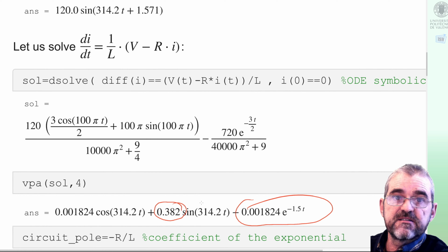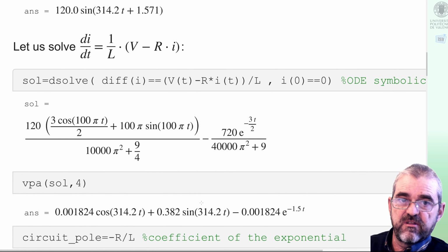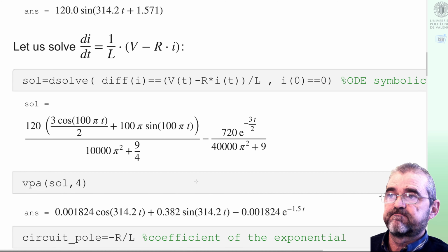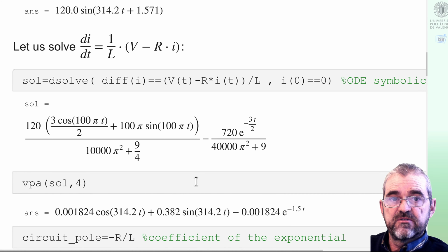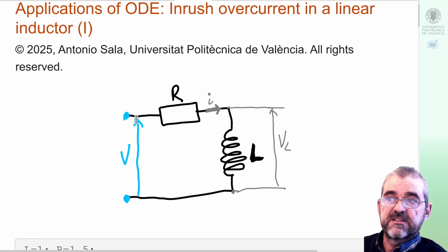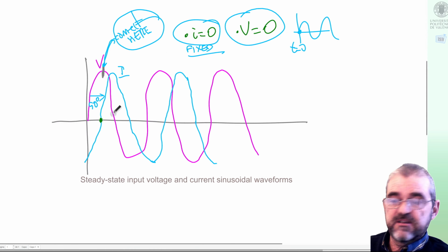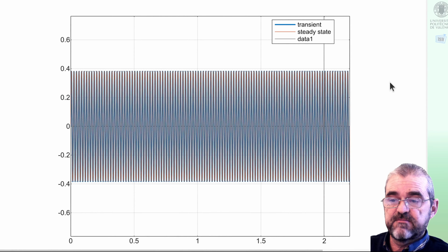It will be exactly zero if we exactly match the timing of the connection with the power factor, but in a basically inductive load, if we displace things 90 degrees, we start the connection of my inductor when the input waveform is at the maximum, then we are very, very close to the steady state AC sinusoidal regime.